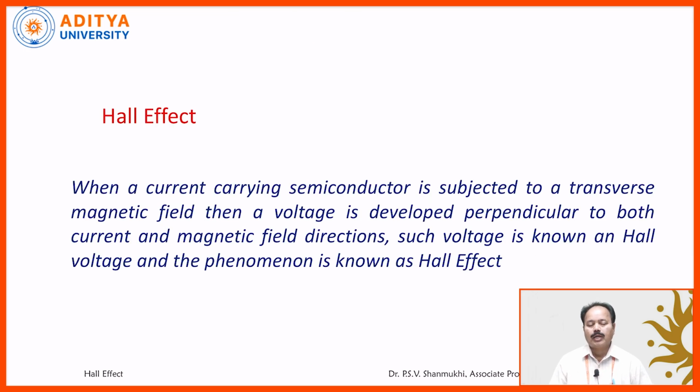Now coming to the Hall effect. When a current carrying conductor or a semiconductor is subjected to a transverse magnetic field, then a voltage is developed perpendicular to both current and magnetic field directions. Such voltage is called Hall voltage and the phenomenon is called Hall effect.